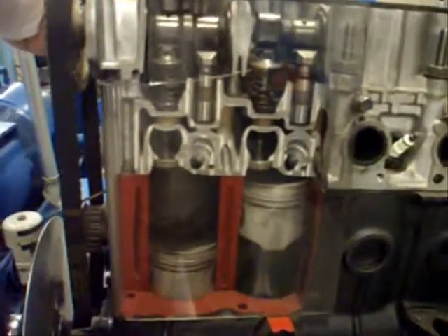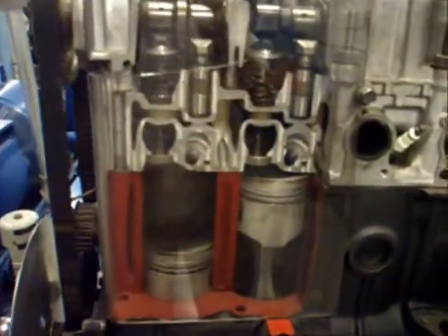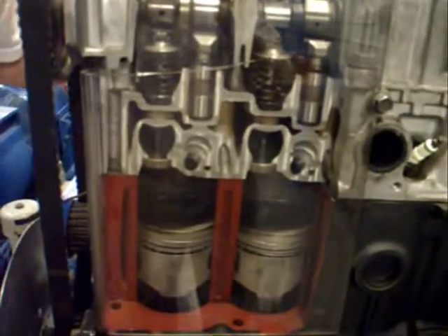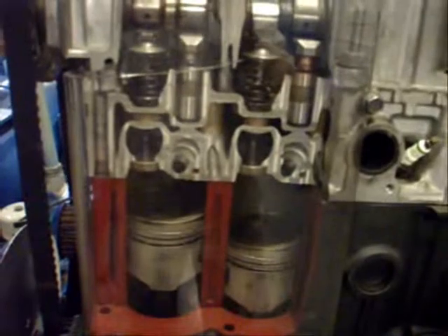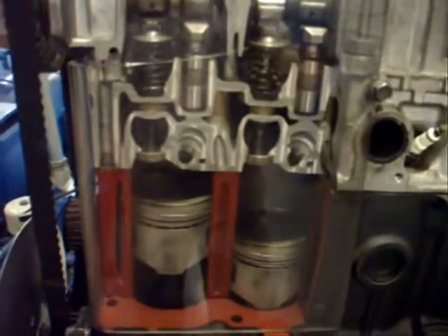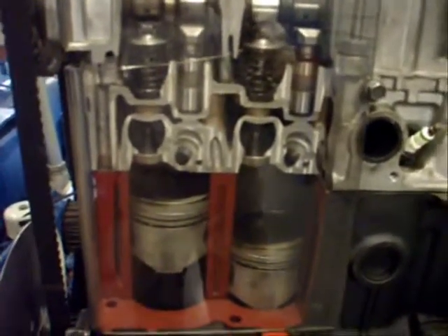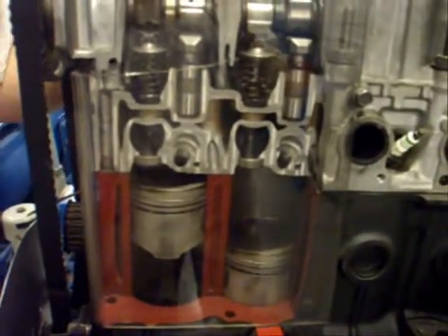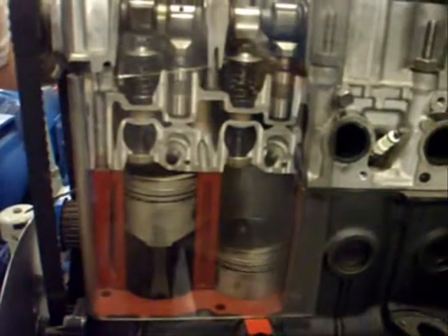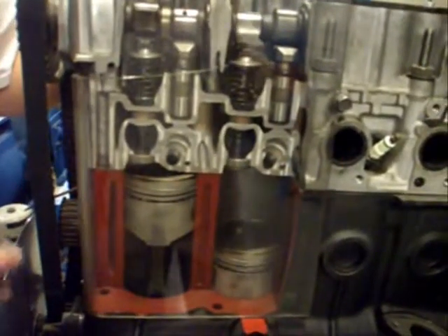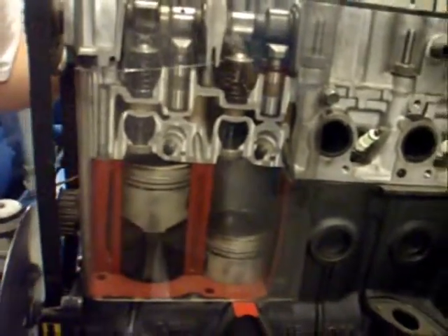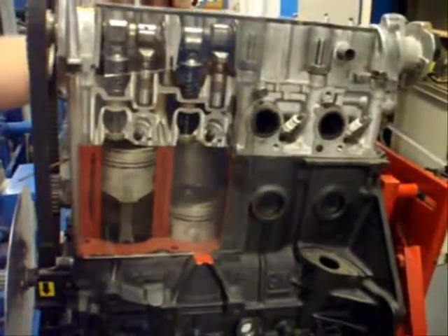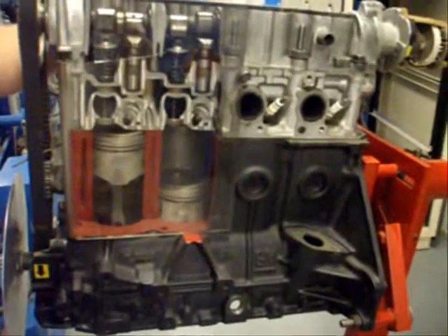Okay? So when we advance the timing, if we're watching this number 1 cylinder, as the piston comes up, if we advance the timing, the spark occurs earlier, like right here. As the piston's coming up, if we're at baseline timing or the traditional timing, it might occur here. And as we retard the timing, which means it occurs later, it might occur closer to top dead center. Ignition is always going to happen before top dead center, but we can adjust it so that it can occur earlier or later than our baseline timing.